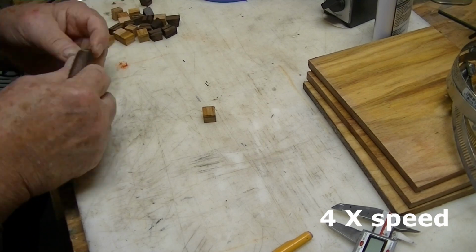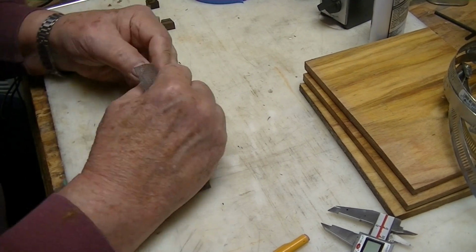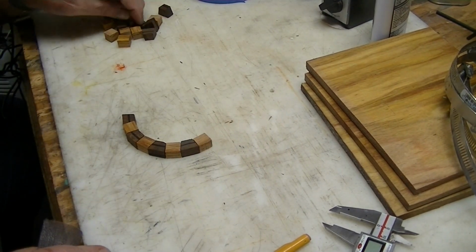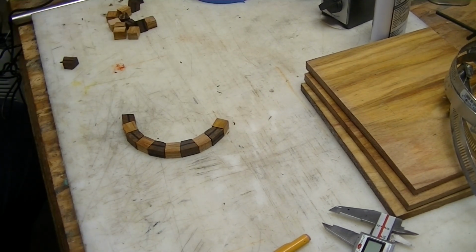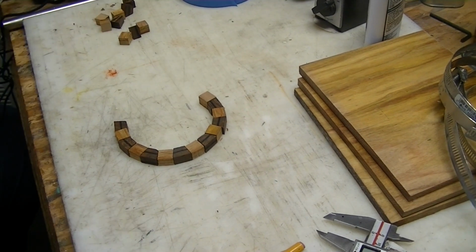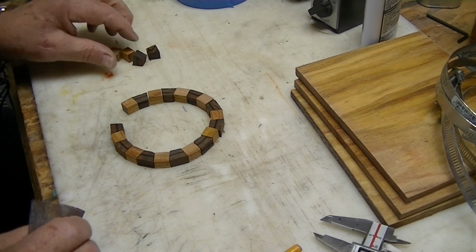So what we're going to do here is sand each individual one, and then I'm going to mix the segments and the spacers, keeping all the segments so that the face is up on all of them. The edge on the front side of that piece of wood is alternated inside and outside. These alternations help keep the wood perfectly aligned. If there's a small error in my table saw, that's accounted for by these adjustments in the settings.